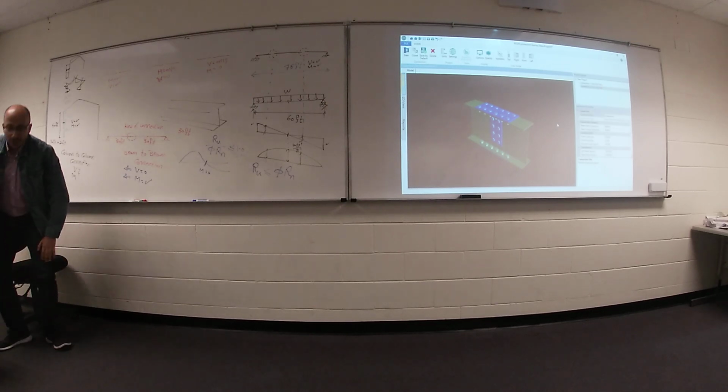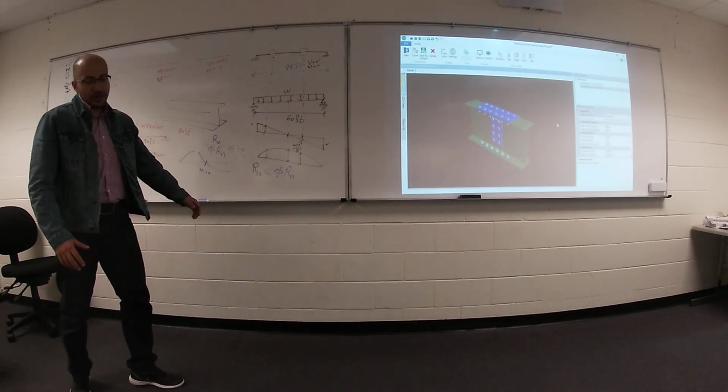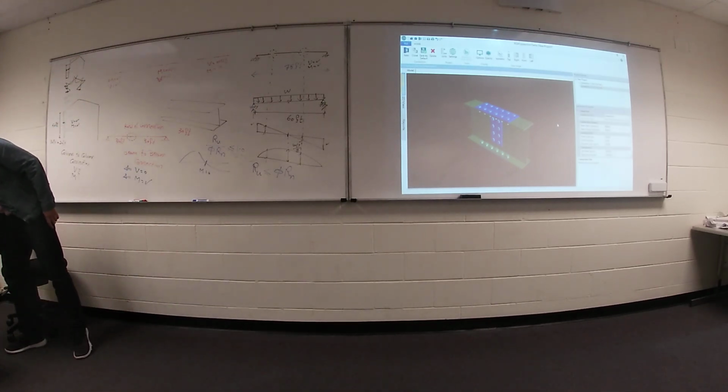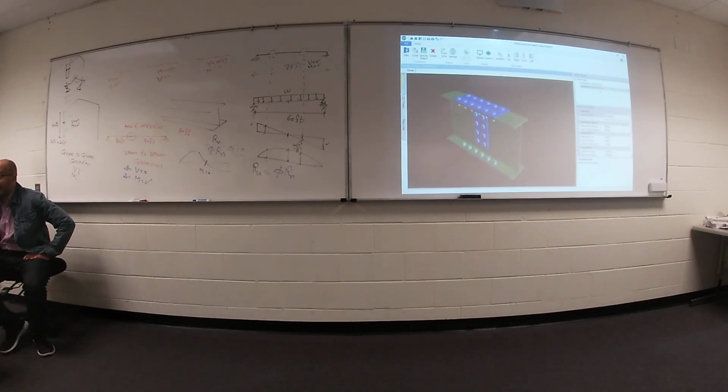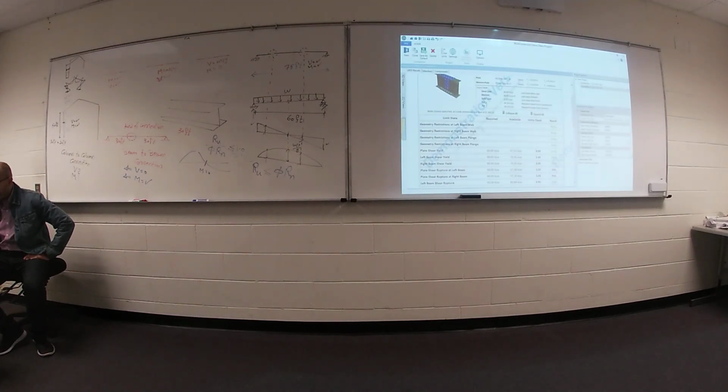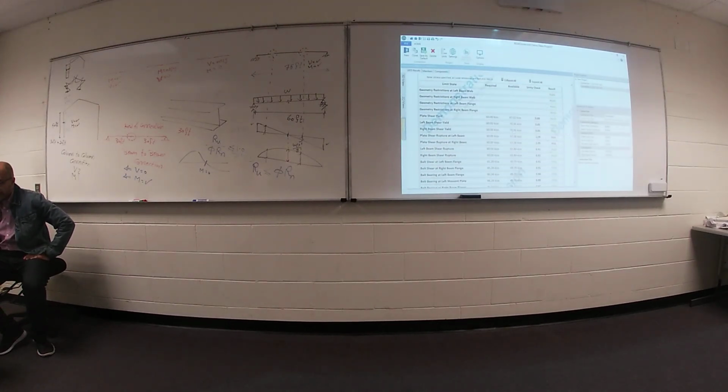Anyway, your connection right now will support moment and shear. Still fail. We have something wrong. If you would like to see what's wrong, go ahead to the report. Everything is fine except plate shear rupture. We have an issue with the plate supporting shear.